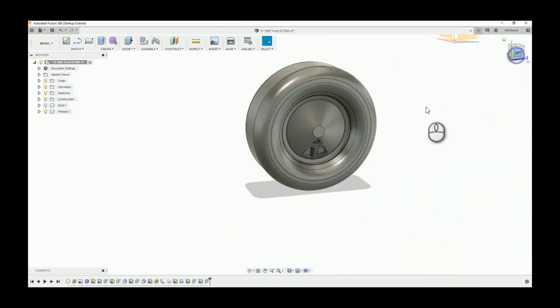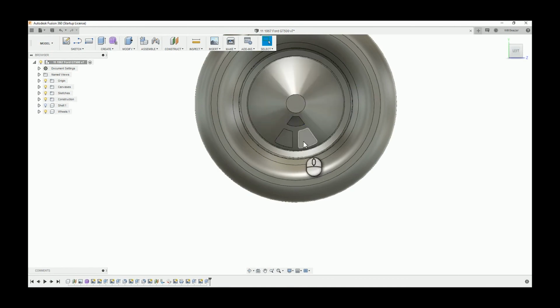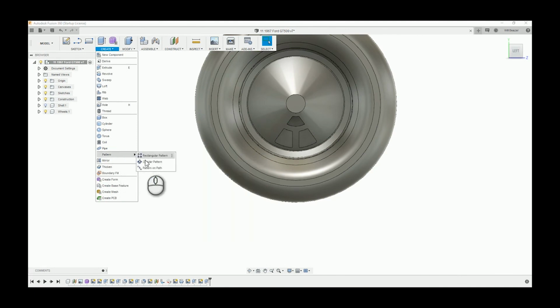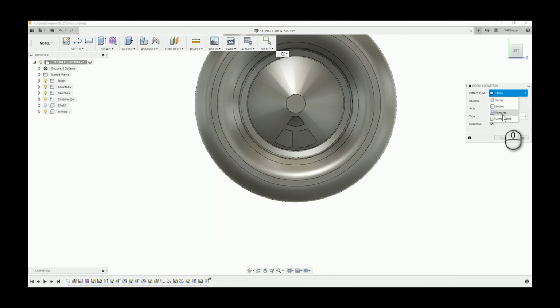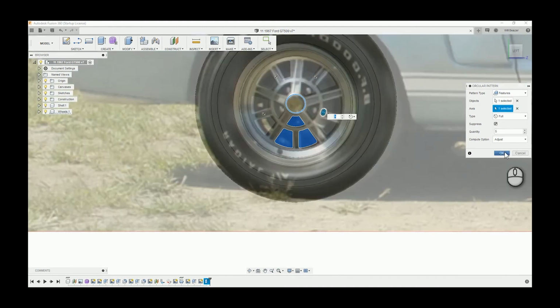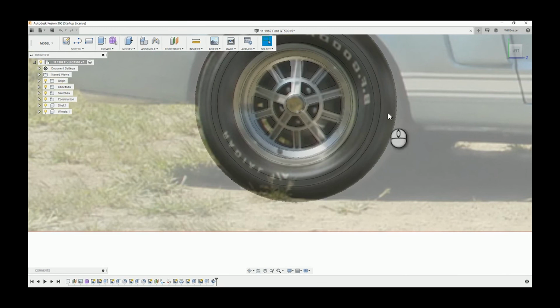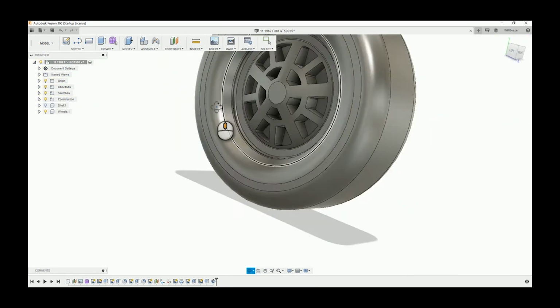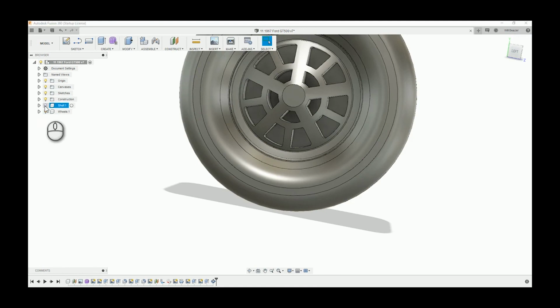and then for that feature, I can go into create circular pattern, click features, select the cut feature that I've just done, and rotate it around the axis. You can click any circular face on that wheel and it will do that, and then up it to 5 things to pattern, and there we go, that fits the wheel basically. That saves me a lot of time rather than doing that sketch process all over again.